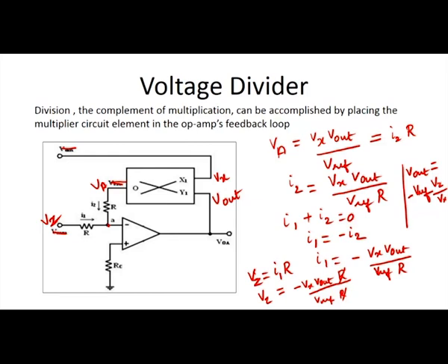So Vz is divided by Vx, and these two voltages are given externally. Vz divides the voltage Vx and it is multiplied with the constant voltage V reference here. So in this way, this analog multiplier is used as a voltage divider.